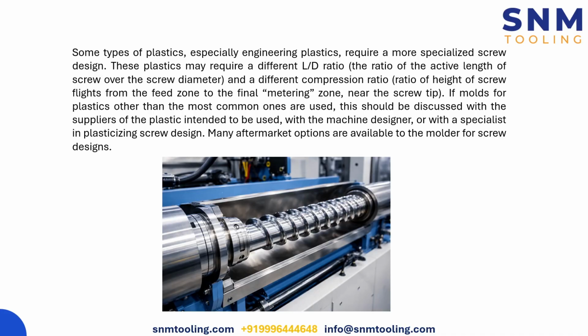And when it comes to polymer types like PP, HDPE, or if it's a filled or an unfilled polymer, for example, a glass fiber filled polymer, or a mineral filled polymer, or a flame retardant polymer. And it also depends how sensitive the material is with respect to heat, how abrasive the material is, and lastly, how sensitive the material is to moisture.